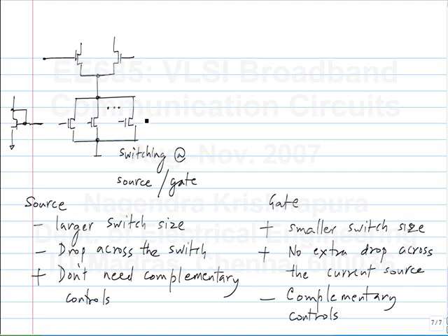Yeah, if you use PMOS, that automatically interprets the control as a complement. So where do I use the PMOS? I use it here, and I use it here, and I can do this. Okay. So this way, when this is low, the NMOS is off, PMOS is on, and when it's high, the NMOS is on, so the current source is 0.